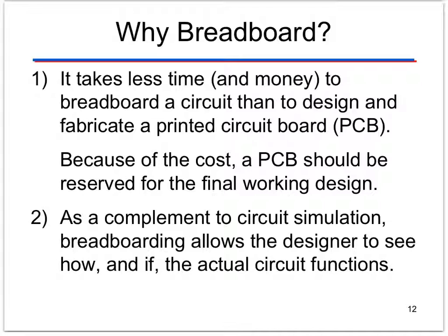So why do you breadboard? Well, first off, it takes less time and money to create a circuit. Because of the cost, a printed circuit board should be reserved for the final working design. When everything is done and you know it works properly, then you can make a printed circuit board. We won't be making printed circuit boards here except one time, and that's just the random number generator early on in the course.